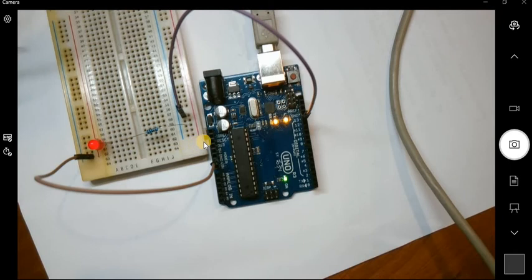So you can see now I've actually paused the video for a moment and moved the wire connected to this LED also to pin 13. So both of these LEDs, the built-in LED on the PCB and the LED on the breadboard, are connected to pin 13. Now this other LED is just showing any activity on the USB communication link to transmit. So every so often when I turn on the LED, I'm actually sending a message as well.